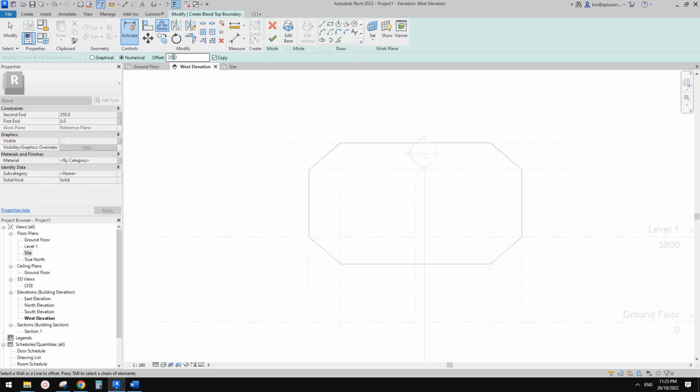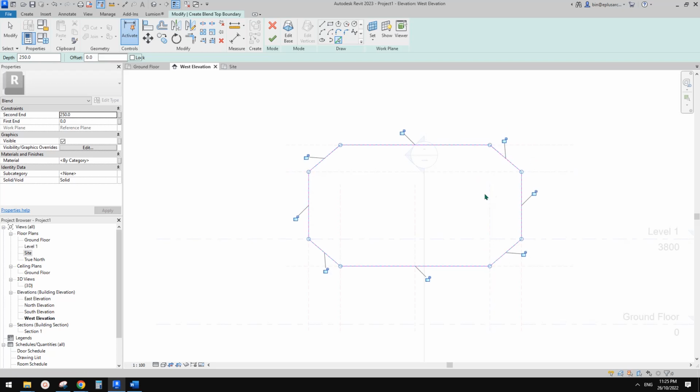Okay. So we just type in a number, or we can just use graphical. If you click on graphical, Revit will let you, hang on, we need to pick line first. Sorry, just pick line, create all these lines, and use offset. So I'm going to just uncheck the copy, so once we offset them, Revit will delete the original lines. And also we're going to use graphical, so let's just tab. Looks like we can't do it this way.